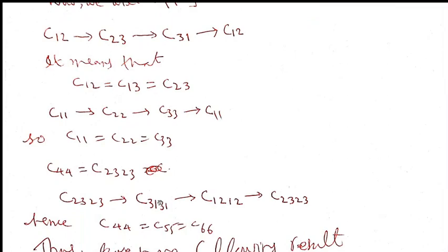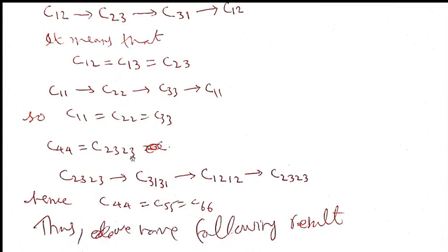Now we have the other three diagonal components, which are C44, C55 and C66. C44 is basically C2323, since we have no 4, so we write this 4 in four index notation: 2, 3 and 2, 3. Applying 1 to 2, 2 to 3, 3 to 1, this gives us 3, 1, 3, 1. Again, 3 goes to 1 and 1 goes to 2, giving 1, 2, 1, 2. So this gives us C44, this is C55, and this is C66.